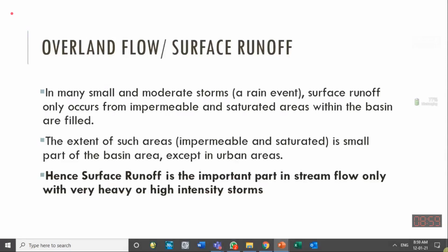We are doing research in this area also, and you people can also continue it. So that is the purpose of the Doongi Ground, or low depressed area, in a housing society, and that is a necessary thing. Don't try to cover the whole society with concrete or bituminous surfaces. Leave some area for recharge of the groundwater. How much it should be, we need to see how much is the effect. Usually LDA says that in every house so much area should be kept as what we call unpaved area.